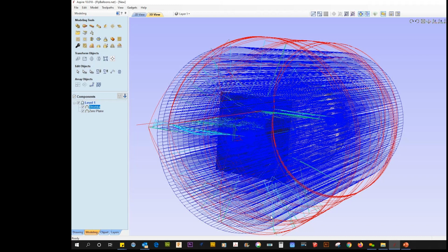I have never roughed with the rotary with a 1/4 inch bit. I've always done using either a 3/8 bit or a 1/2 inch bit. I feel like that's safe to me. I mean, I would do some more testing and see if it's possible for me to run with a 1/4 inch bit and see what's a safe speed to run. But I just have never felt comfortable with doing it, because your initial roughing is a very aggressive cut.